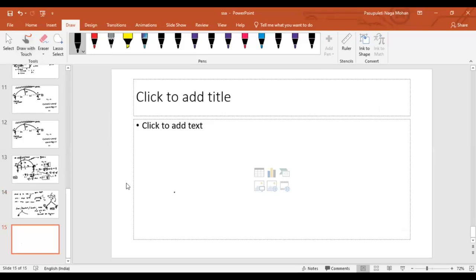One doubt, sir. What is the relative stiffness? Let me tell you. If the far end is fixed, what is the stiffness we are talking about? 4EI by L. If the far end is pinned, it is 3EI by L, right? So let us normalize with 4E. Everywhere divided by 4E, it will be I by L, and here it will be 3 by 4 I by L.